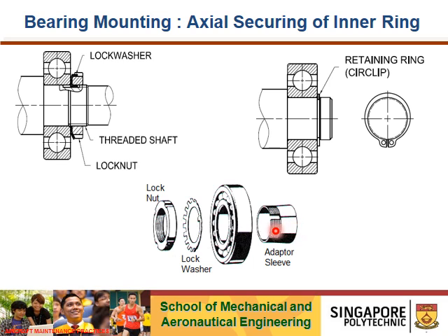Then the manual will in fact ask you to loosen it and tighten the lock nut at a lower torque value, maybe about 200 inch-pound to 300 inch-pound. So it's just a number. The first torque is a force applied to seat the bearing onto the adapter sleeve. So this is typically what we do for installation of bearings.